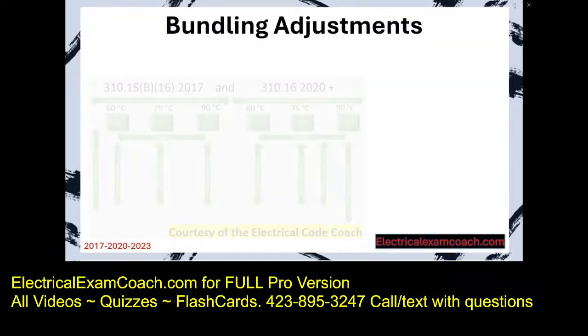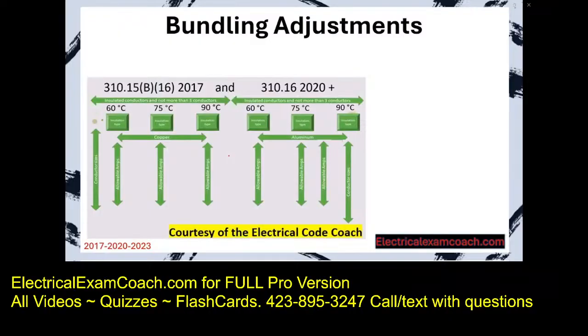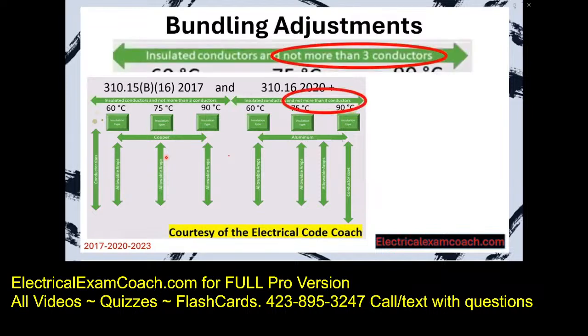Let's take a look at our primary ampacity table. I want you to turn there now. And these values down below this table are true if, well, the question is if what? If you look at the paragraph above the table, the one that I said we would come back and look at later, it's got some parameters there. It says, hey, these are the ampacities of these conductors if, and the first if that we're going to look at is if there are not more than 3 current carrying conductors inside of a cable, pipe, or even buried in the earth together.